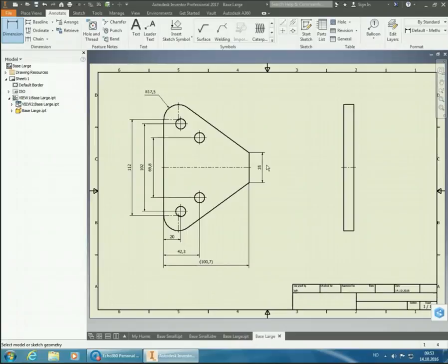Which means that the total length here is pretty much dependent on how you hit your tolerances on these other dimensions. So that 100.7 might not be the actual case when you start measuring this one. But putting it in with a reference point makes it very easy for whoever is machining this part to just put a measuring tool on it and look at, well, it's approximately 100.7. And since he can see the parenthesis on the dimension, he also knows that it doesn't need to be exactly 100.7.